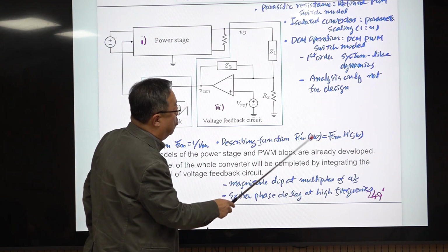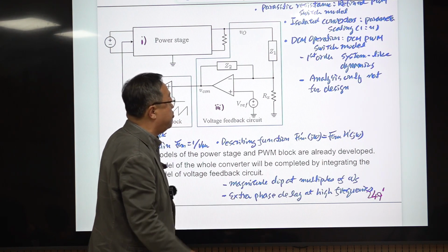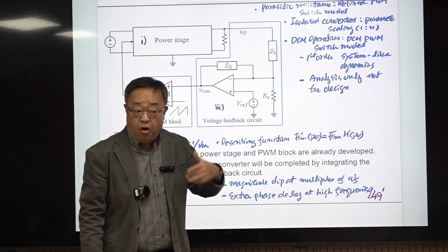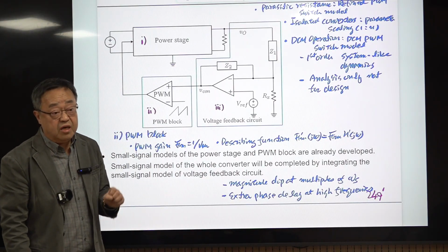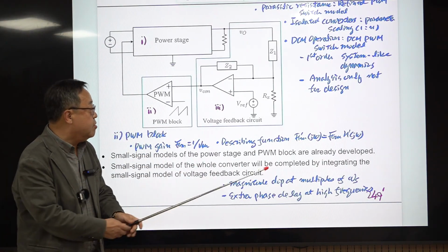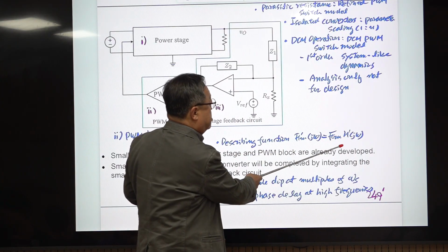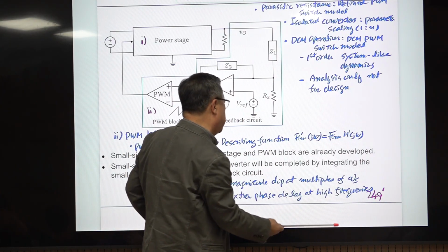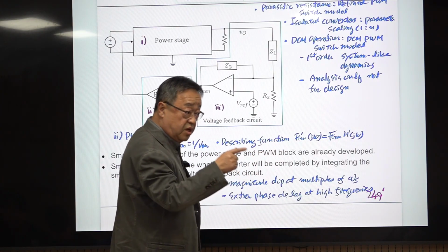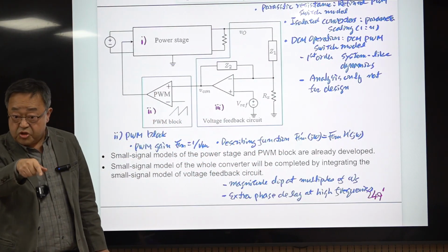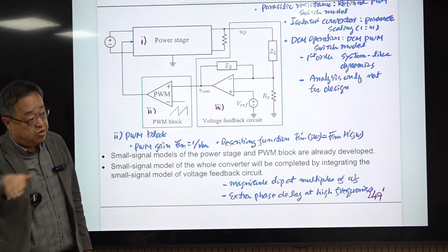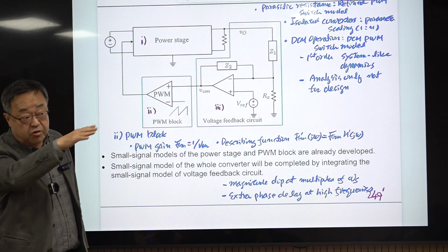It is a function of omega, and it is also a function of the magnitude of the excitation signal, a nonlinear term here, but it can be simplified with some assumptions. So this FM prime of j omega is some sinc function. The magnitude is this sinc function, and it produces the delay at high frequencies.